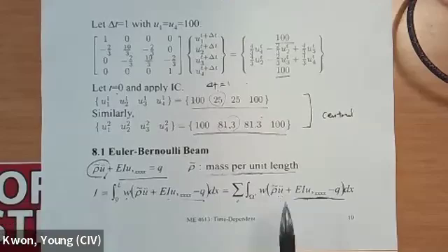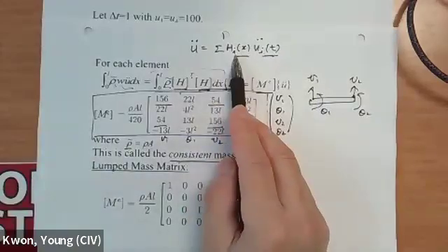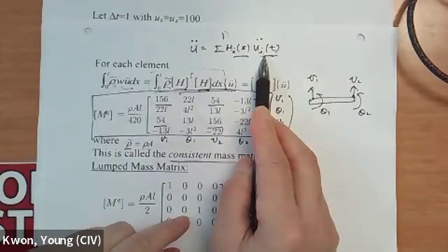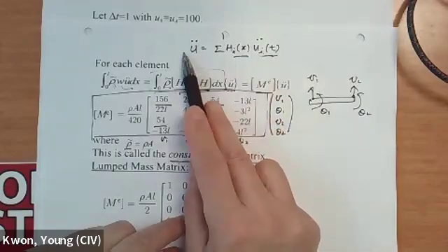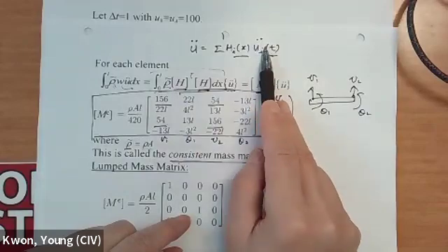This term, as we discussed last Tuesday, is u equals the summation of H_i times U_i, the shape function multiplied by the nodal value. But the double dot, the temporal derivative, is carried by the nodal variable here. So U_i, the nodal displacement, with a double dot means acceleration.